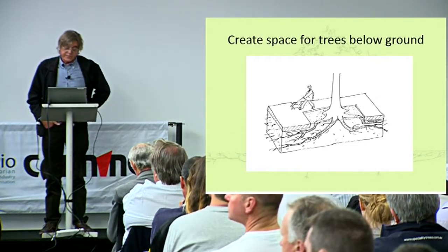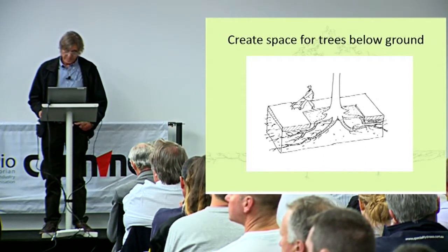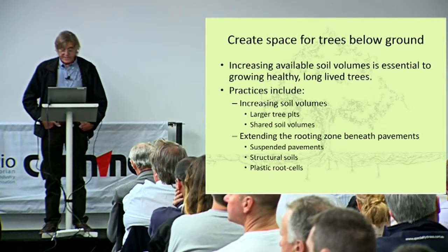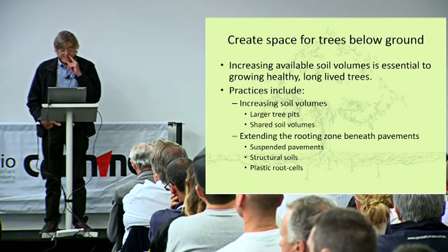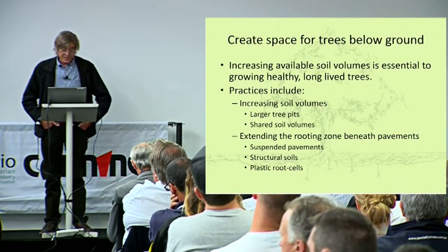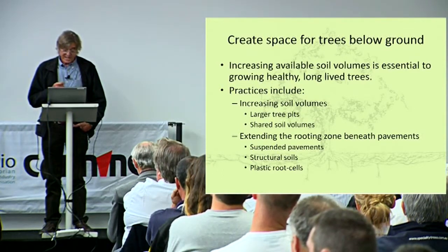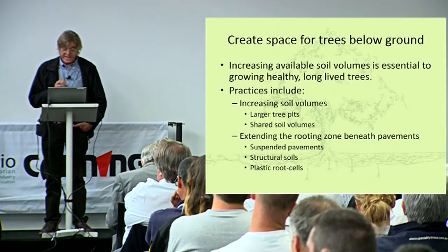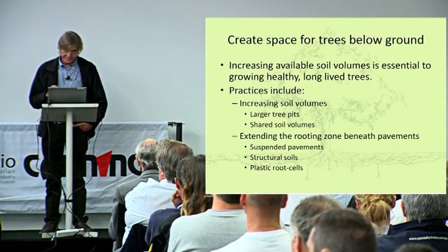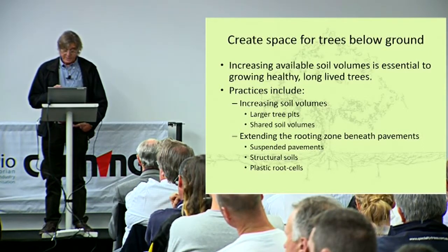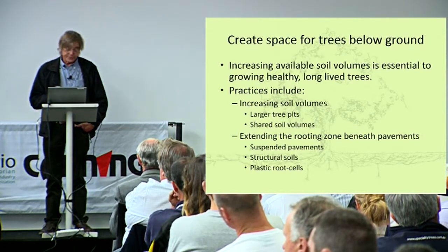Next I'm looking at creating space for trees below ground, which relates to what we're talking about today. Increasing available soil volumes is essential to growing healthy long-lived trees. There's a whole range of practices which include increasing soil volumes using either larger tree pits or shared soil volumes. And the second group of practices relates to how you extend the rooting zone of trees beneath the surrounding hard pavements. A number of options there were discussed earlier. One is suspended pavements, structural soils and plastic root cells.